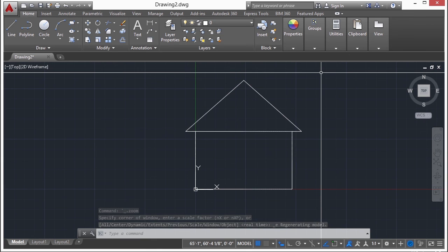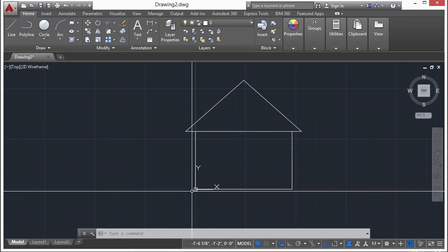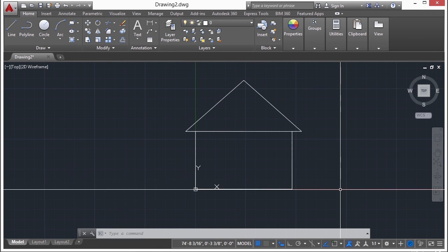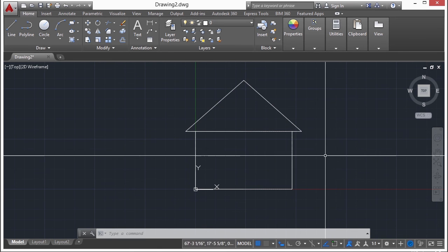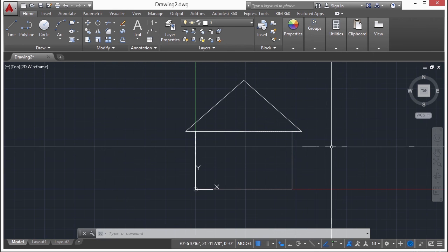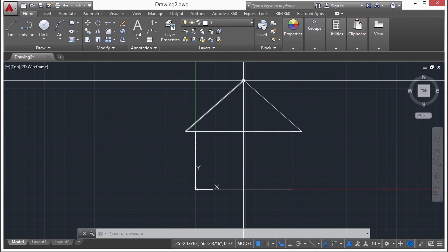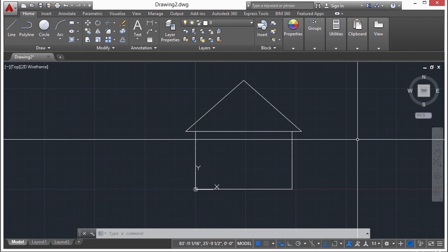Now this is very simple right here of what we've just done, but that shows you a lot of different ways that you can draw different lines using different types of methods. We did some absolute coordinates, absolute lengths. We used the ortho command to help us lock it in vertical and horizontally. We also used some relative polar coordinates, so we can draw in that way as well.